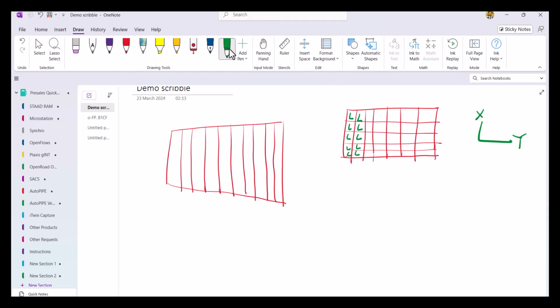What is the benefit out of this? Whenever you are getting a moment against which you are going to design the reinforcement, the moment that you are going to get, for example, is something like MLX or MLY. These are all known as the local axis moment. Okay, what is the local axis moment? It means moment computed about the local axis orientation.